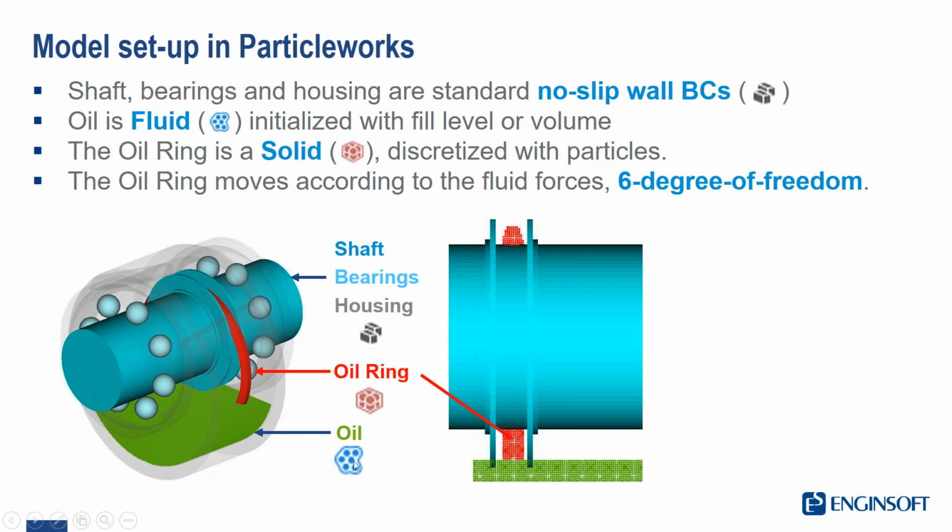surrounding elements. And then we have the oil volume down here that was initialized with a filling plane. So we just needed to define a point and a plane, and below that plane, the oil was initialized. We could also have used a solid, the fluid volume from the CAD, but Particle Works also enables this option of the filling plane that in some cases is much easier.